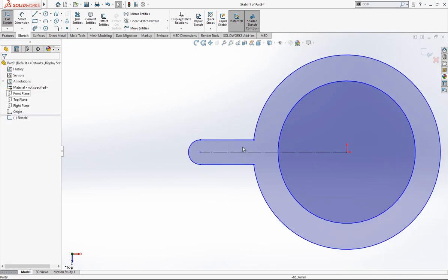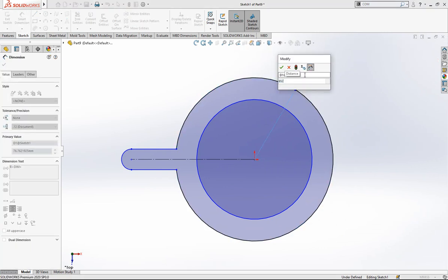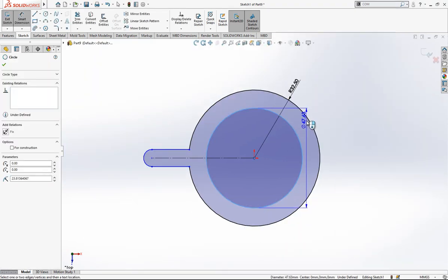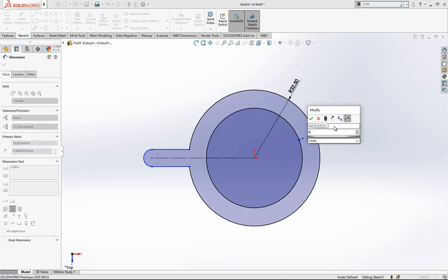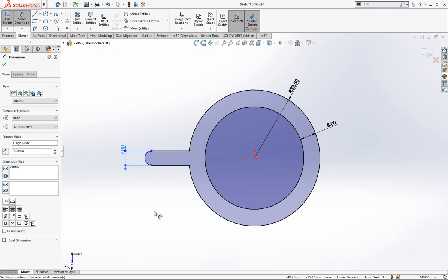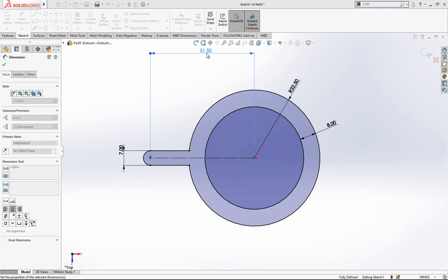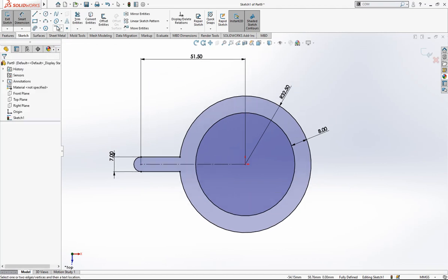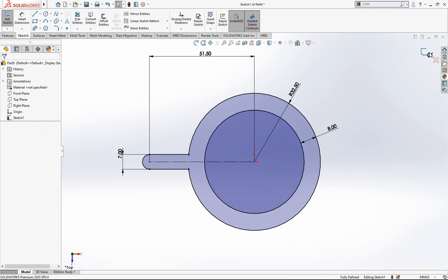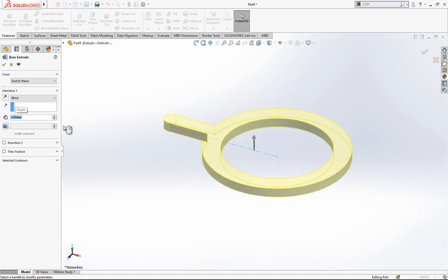It's okay. Now dimensions. Outside is 65, because it is a radius I divide by 2, and we have here an 8mm ring. This will be 7. From center to here we have 51.5, and then I can continue to other operations in another sketch. Let's not make it that complicated. And I make an extrude for 4mm.